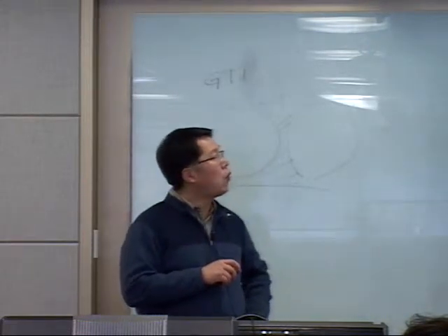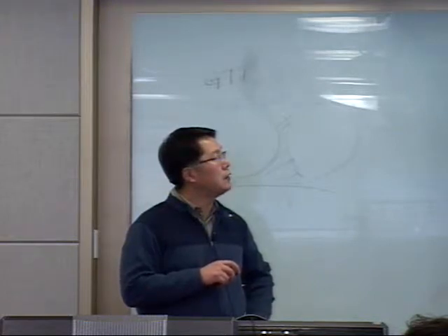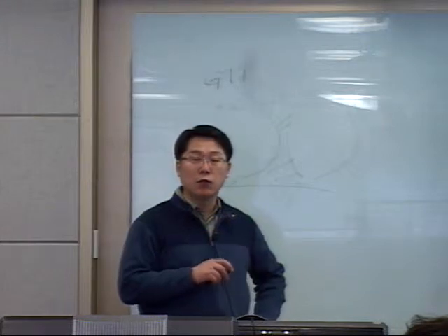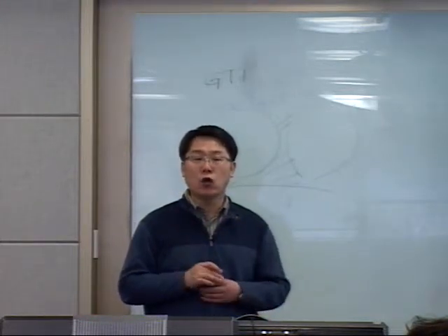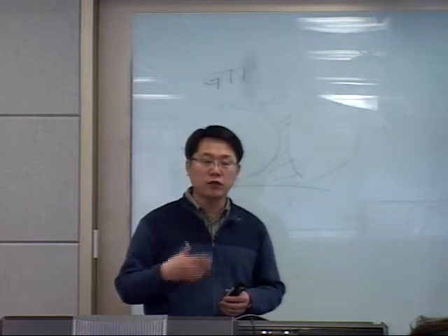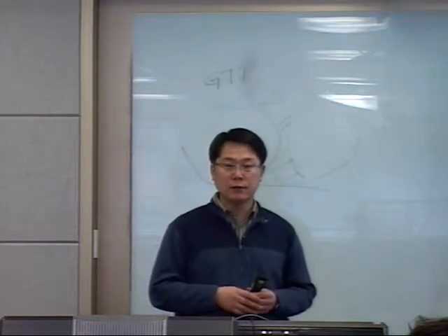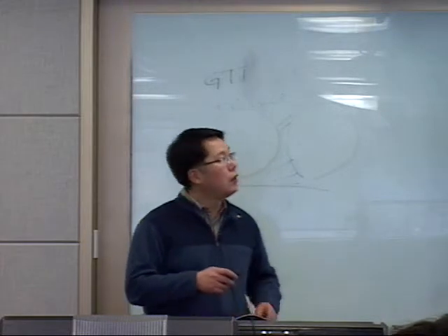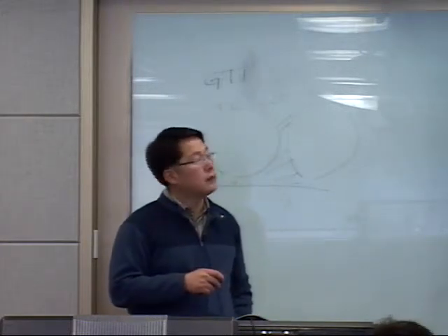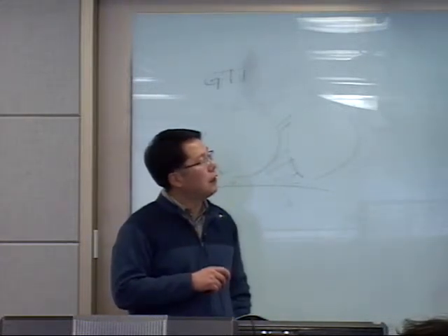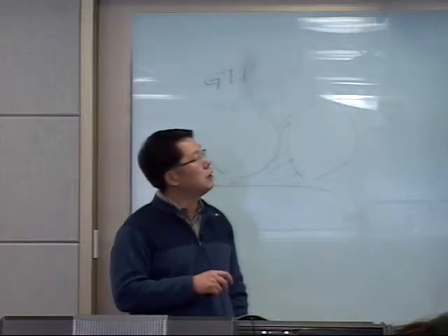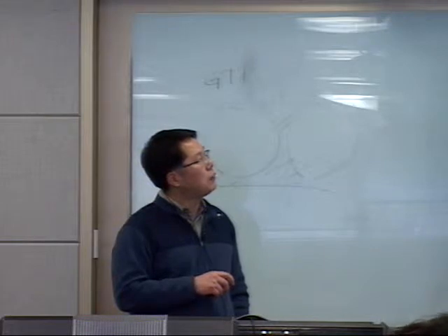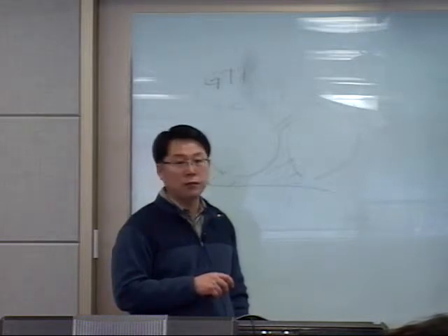If cold BOG is inserted into the compressor, we need a special compressor to handle the low temperature gas. So the policy taken in this process design is to exchange heat between this stream and this stream.